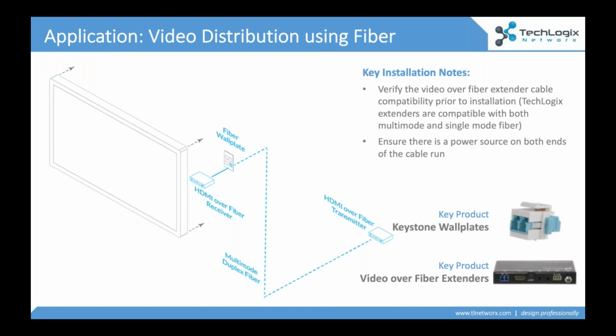So when we talk about 4K, we talk about 444 color space and 60 frames per second and HDR. We're talking about 18 gig in bandwidth. If you want to send a native 4K signal, you have to incorporate fiber optic cabling. And certainly, if you want to future-proof your installation for 8K, which you can go out and get 8K displays and projectors now. There is 8K content. This is part of another course that we teach here at TechLogix and that we've taught for CEDIA now for quite some time. And now Bixie's, we're teaching Bixie integrators the same content. These bandwidths, they're getting pretty big, and you need an optical cable to move them around.